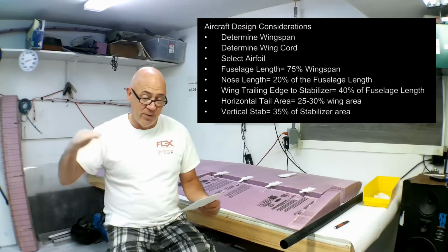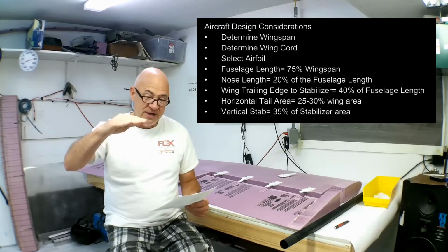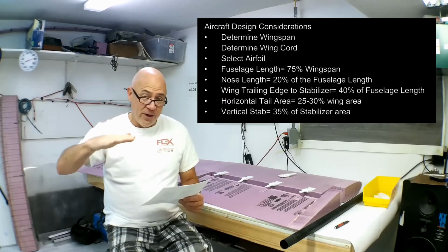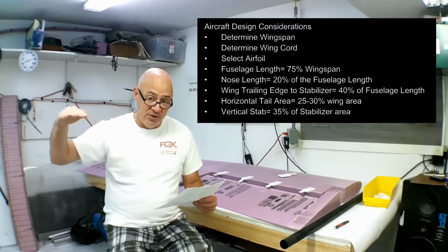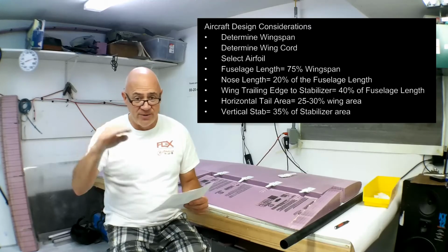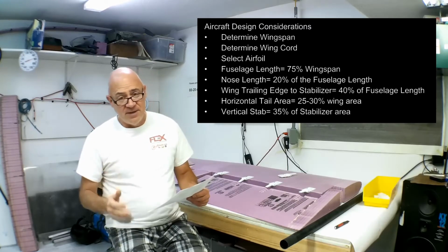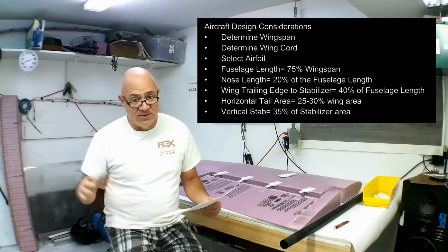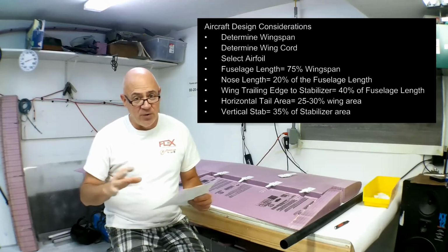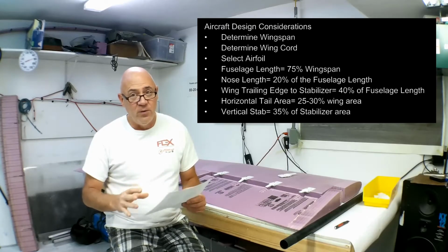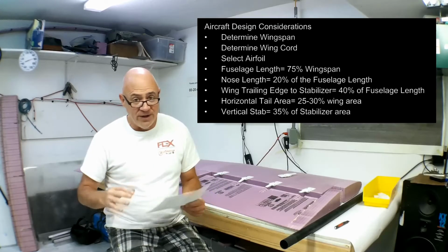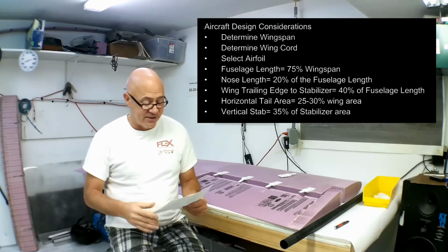The reason is that when you go fast with a semi-symmetrical wing, it just takes a little bit of down trim to fly level. A flat bottom wing will want to produce all kinds of lift, so you need a lot more down trim. And a fully symmetrical wing sometimes doesn't need to have much trim change. But semi-symmetrical wing is the most forgiving when it comes to slow speed. I'm sorry, that's not true. For a scale airplane that you want to keep scale, a semi-symmetrical wing will give you the greatest flight envelope and slow speed characteristics. A flat bottom wing gives you the absolute slowest characteristics.